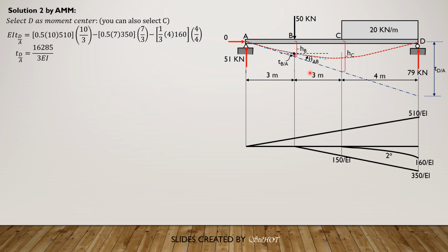Then we have a horizontal line through this point on the elastic curve, so that the tangent at B from the horizontal line is clockwise, so it is expected negative. Theta B is expected negative.